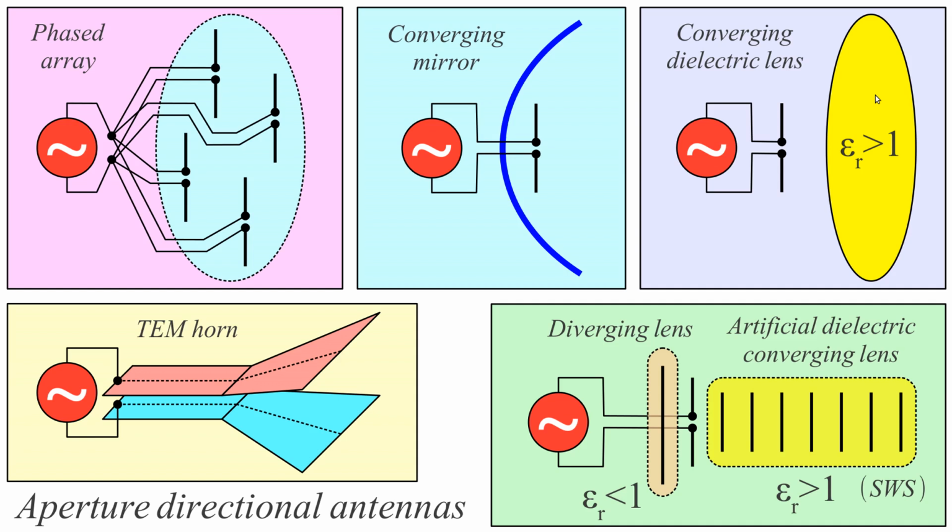And here we come to another idea with antennas: build artificial dielectrics. Artificial dielectrics made from differently shaped pieces of metal, like metal rods. I can make some space behave as a dielectric with an effective dielectric constant, effective permittivity, relative permittivity, larger than 1. This is also called a slow wave structure. Slow wave because the waves are slowed compared to the free space.